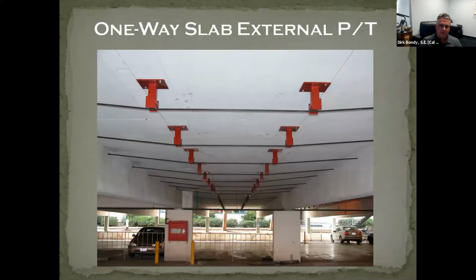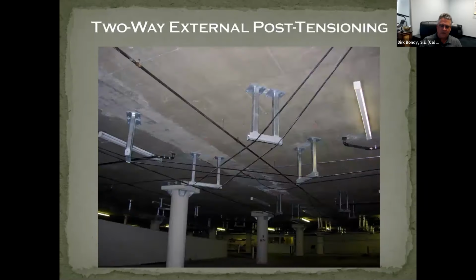So, one-way slabs. This was a job actually in Newport Beach, not too far from here. This was our final product for fixing a slab only. I'll back up. It turned out that they didn't do a good job of sealing the top deck, which they promised they would. And we had to come back about 6 or 7 years later and apply a new slab up above, and then strengthen the beams and strengthen the girders too.